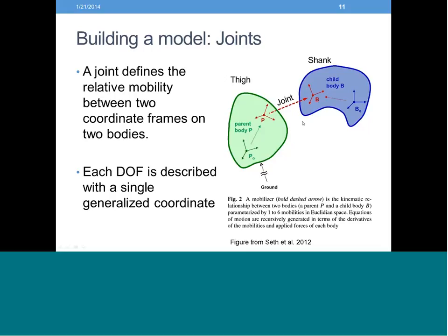An alternative way of forming your equations of motion is to treat every rigid body in 3D space as having 6 degrees of freedom, and then either augment your set of equations with 5 additional constraint equations, or use those 5 equations to eliminate variables.